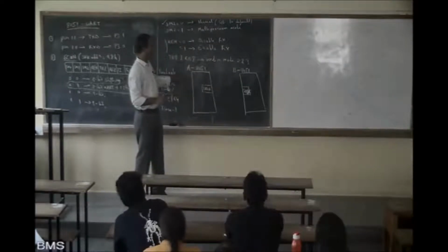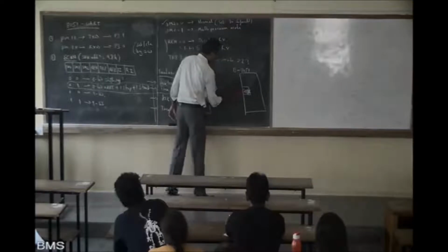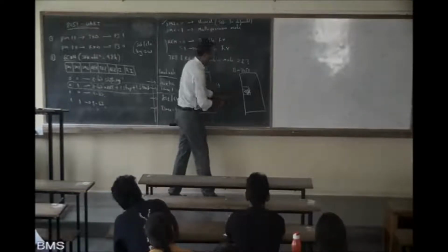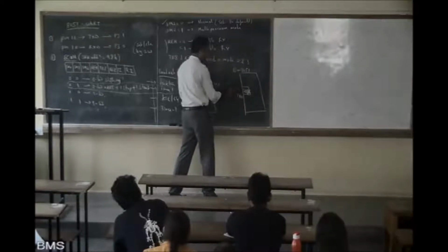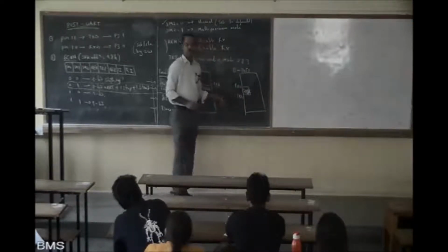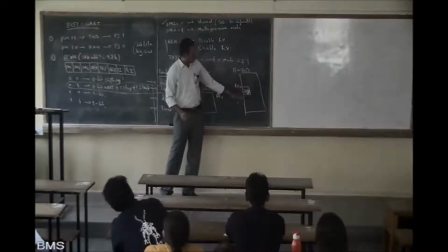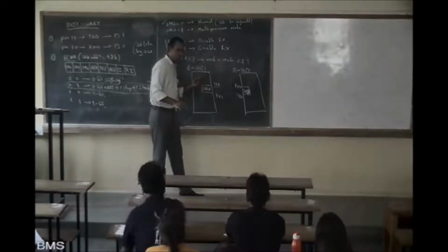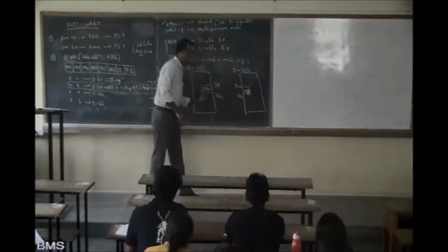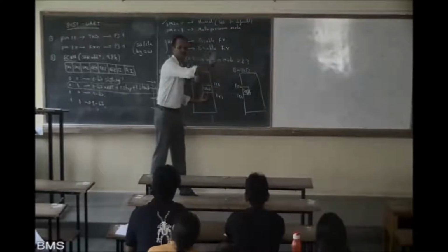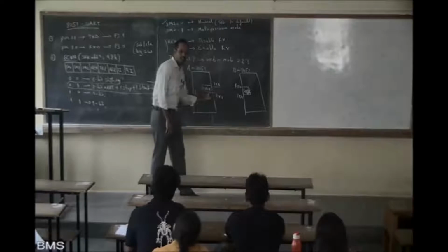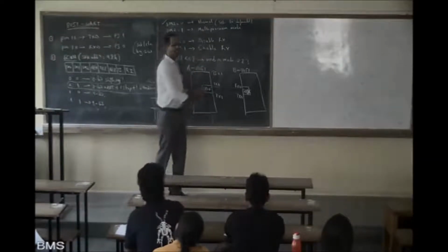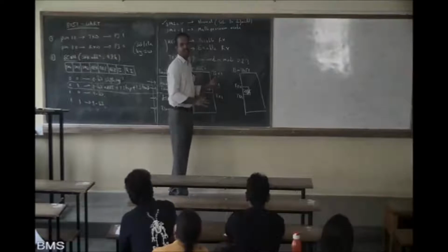The two 8051s, I have named them A and B. Now if I want communication between these two, the RxD will go to the TxD here, and this TxD will go to the RxD here. Transmission here is reception here. If you want to transfer any data from A to B, put it in SBUF and set the timer, it will go. When it transmits the last bit, TI equals 1. That means whatever job was assigned is done, and it sets as 1.